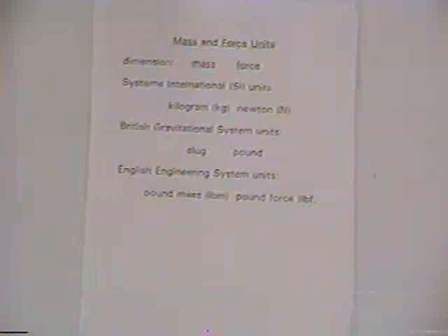And as we talk about fluid mechanics, we'll start with a discussion of fluid properties and go down the list here and define density and specific volume, specific weight, specific gravity, pressure, stress, viscosity, surface tension, and capillarity. As we start with density and specific weight, we'll define density as mass per volume, specific weight as weight per volume. But leading up to that, we need to talk about units just a bit, units of mass and force, and